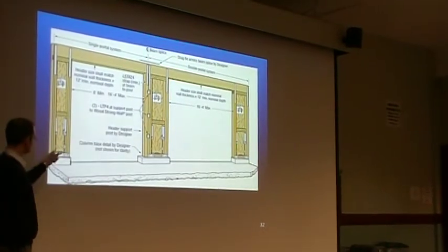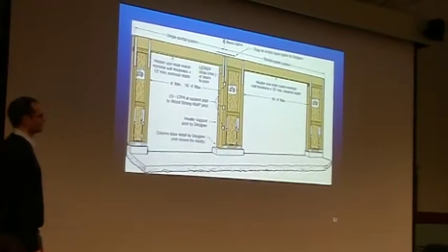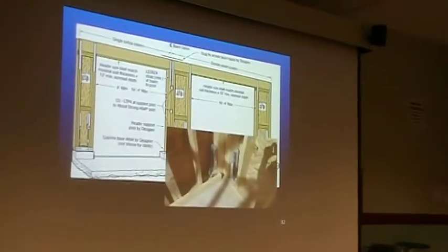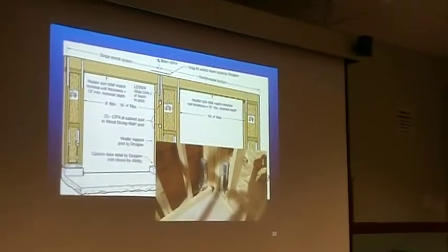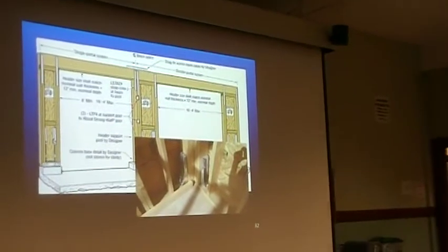Wind blows this way, you've got tension. Wind comes the other way, you've got tension. A lot of people will build these things and wonder why the building falls over. They forgot the tension. That's what they look like when they're installed. Come up with the concept early, then you can figure out the forces later.